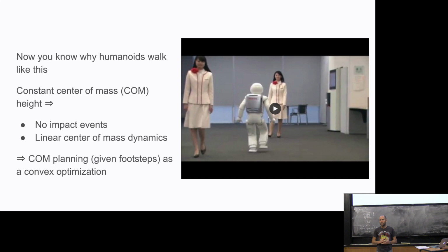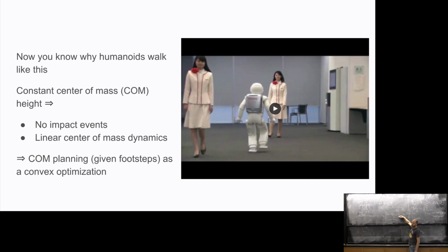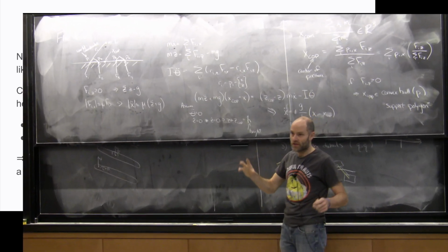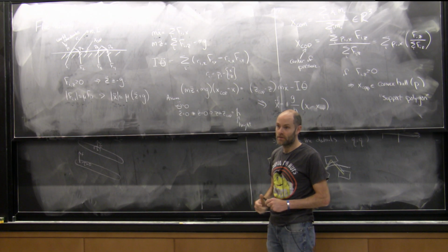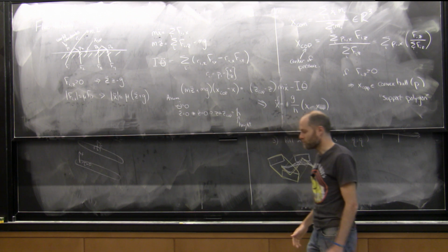But you wouldn't be able to make these assumptions at all if it has an aerial phase where you have to have impact, right? Good. So a similar abstraction technique applies for that. These equations are still not very hard when you have impact, and they still justify thinking about center of mass and angular momentum first, and then filling in your leg kinematics later. So that's completely justified, and that's the recommendation here.